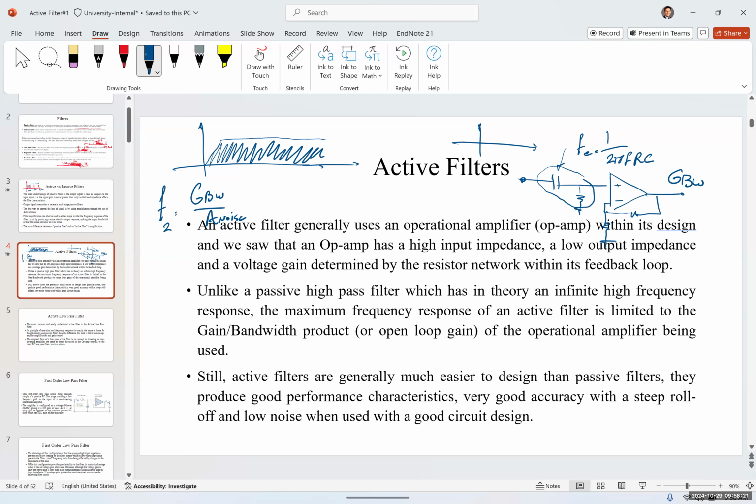But did you have RC filters? Didn't you have RC filters in signals and systems or circuits too? So that is a part of circuits. That's the reason I just touched base on that. Passive filters are a part of that, but that is the impedance that is needed for the RC system. Without that, imagine that R is 0, it's going to create a problem, or it's infinite. You're not going to have a good cutoff frequency. Does that answer your question?